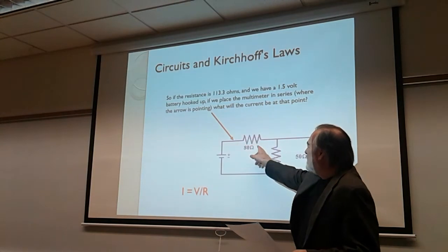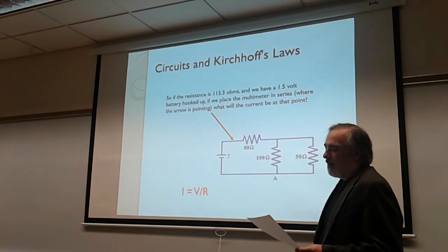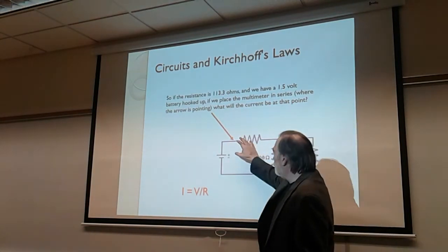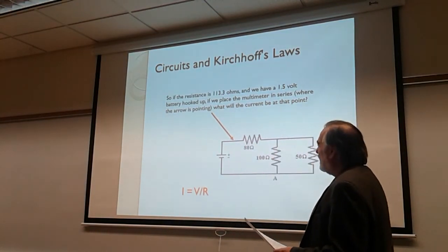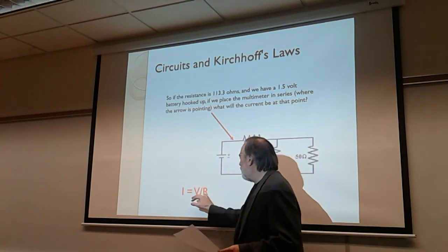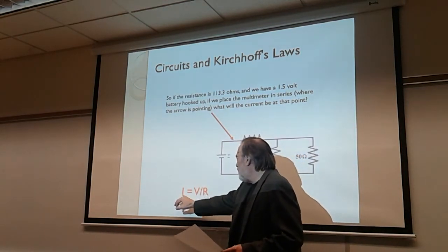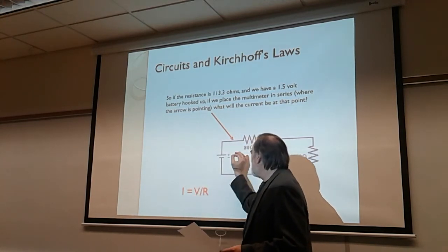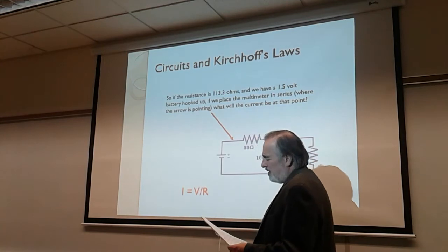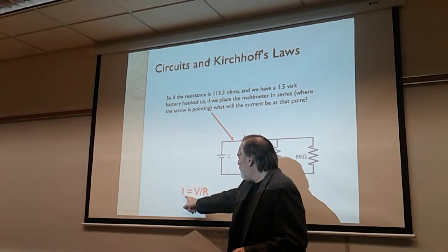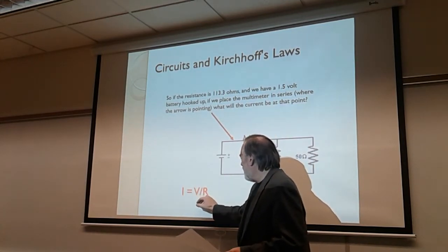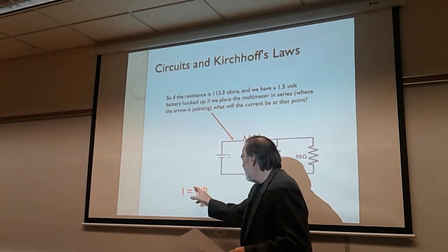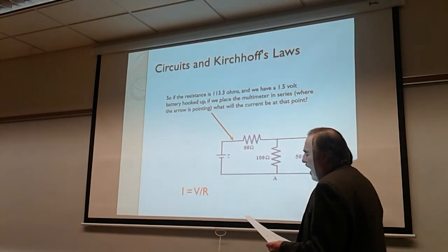When we go into this resistor, that resistor is going to reduce the voltage. Again, we can tell you how much it will reduce the voltage because the current is going to stay the same in the series part, and we know the resistance being 80. So the current being 13.2 milliamps is equal to V over 80, well, that can give us the voltage drop.